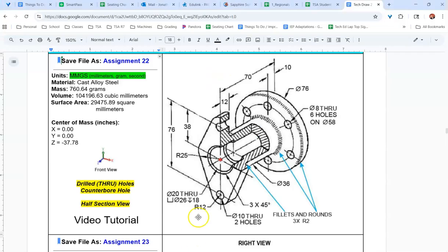Looking back at my picture, I can see over here that I have a big radius of 25. If I follow that arrow back, it shows me that it comes from the origin. So that means the center point is on the origin, and I'm going to be using the center point arc here. I'll click on my construction line and curl up, and I'll stop. I'm not drawing from all the way down here, just from the construction line to here. This is then connected with a straight line, and up at the top we have another little curve.